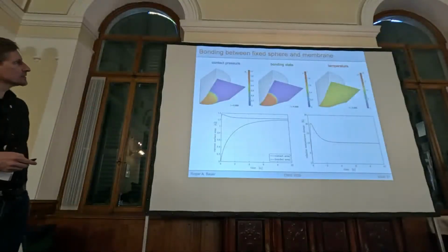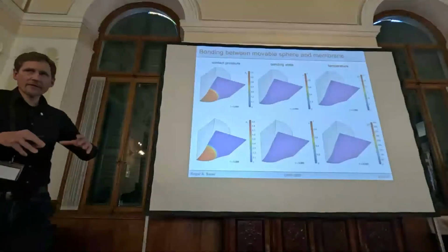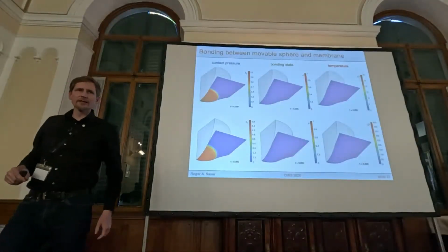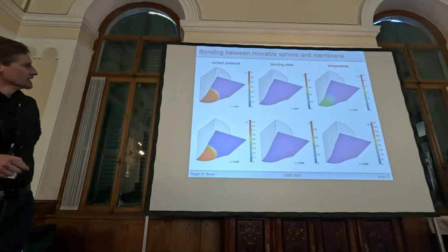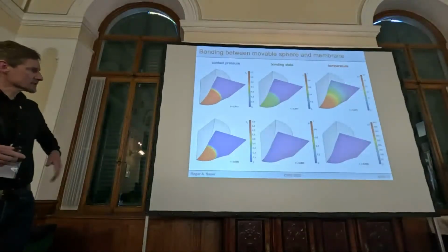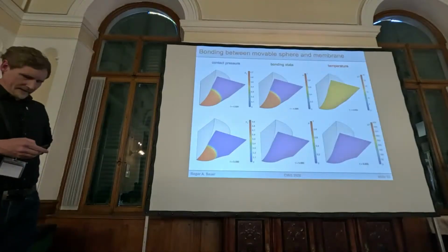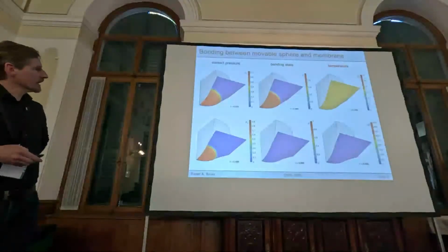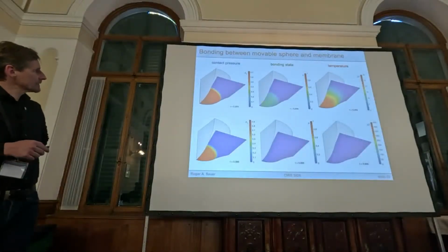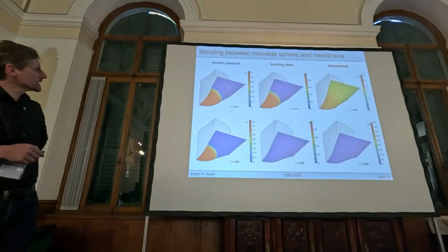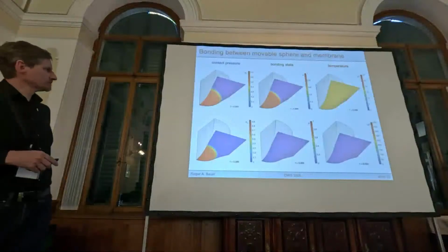If we allow the sphere to move, so that's the second example, then we're expecting, because of thermal expansion, that it will simply drop down. It will come lower, and so we can see that. In this case, the thermal expansion is quite large, and the temperature increase is also significant, so I can run it again. The sheet is coming down significantly and as a consequence, contact area is increasing, and pressure is going down a bit because in this case the contact force was kept constant. So the net force is the same.